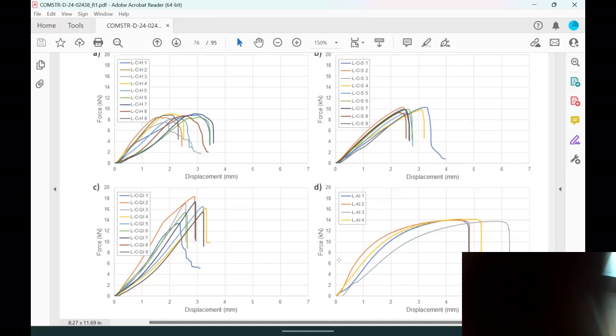None of that. If you look at a cross ply, as I said, the hard laminate, the cross ply, how much does it go up to? 9.5. What's for the aluminium? 14. So if you use a soft laminate, which is all angled by 45, minus 45, how much is it? 10. Even 10. This is the stiffest one, but 10. That one, which is not as stiff, is even better than the stiffest one. Okay. The quasi-isotropic one, how much is it? 18 compared to 14.